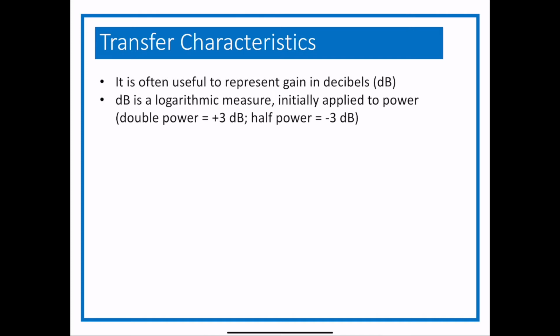If you take half the power, you're decreasing the power by 3 decibels. So oftentimes in amplifiers, we want to look at where half power points are, and that's when the power is 3 decibels less than the maximum value. And it's a little easier to find that graphically and represent that if we're using decibels versus trying to find halves and so forth.